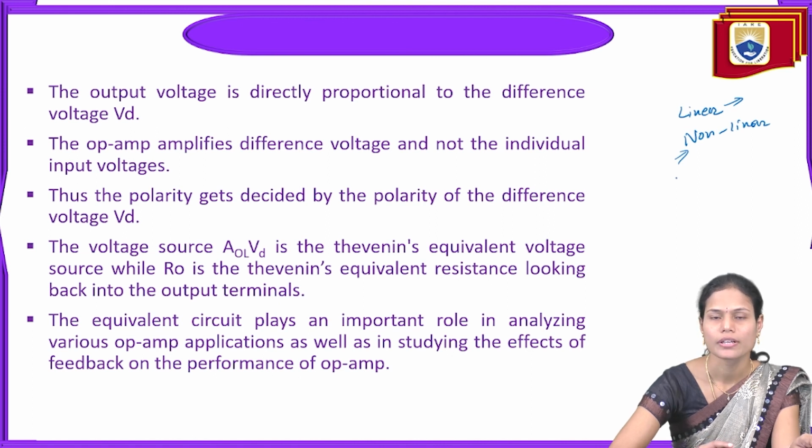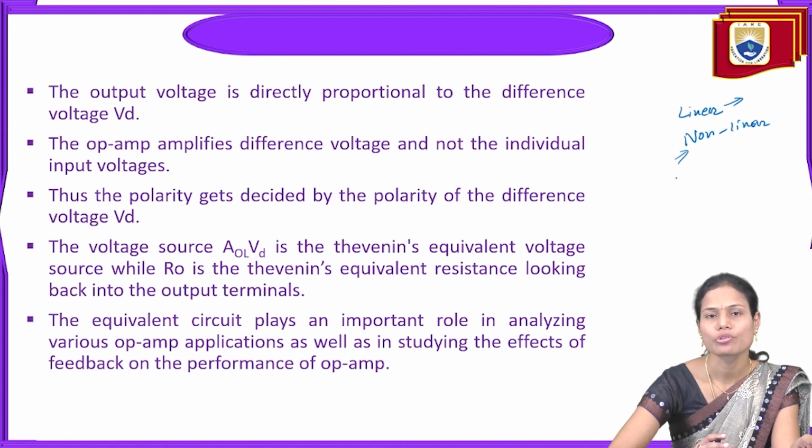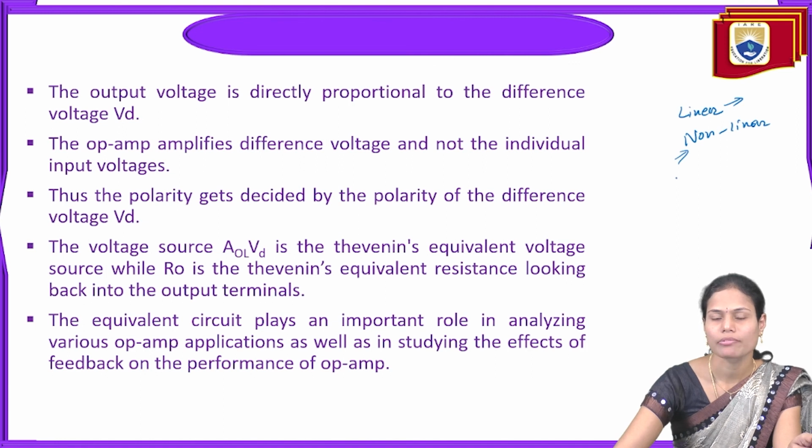Oscillator means it can generate signals without providing any input signal. So we can design the oscillator circuit by using this operational amplifier without providing any external input voltage. To make it a waveform generator, we need to provide both feedbacks at a time, positive as well as negative feedbacks, to generate the triangular wave. And to generate the square wave signal, we can utilize any one of the feedback signals here. The applications of this operational amplifier we will discuss in the next session.